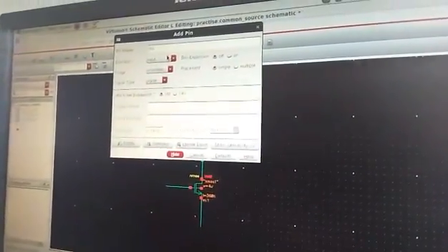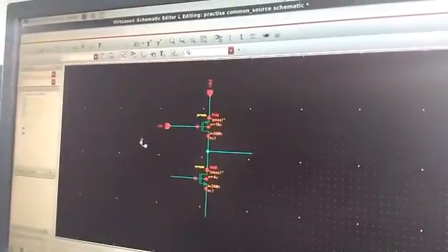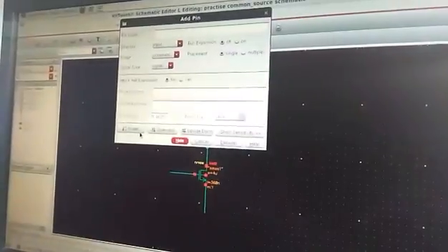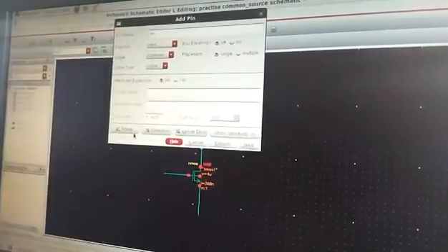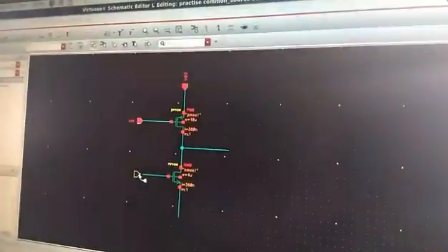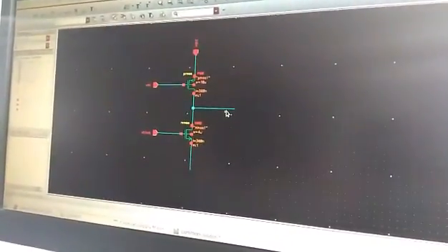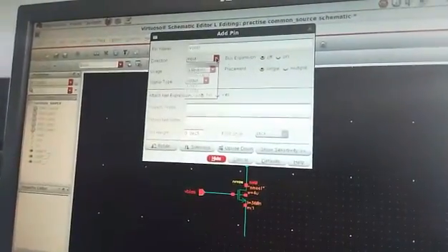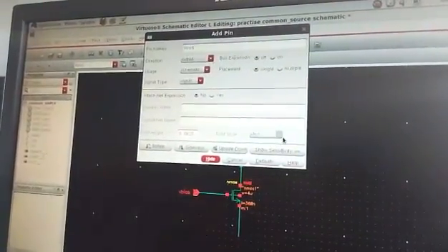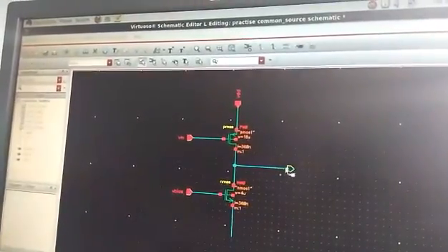And there's one more thing to be added. What I've observed from you guys is you're a bit confused about whether to select a pin or a GND ground to place at the bottom. Well, it's always the pins in this window and the ground in the test schematic.